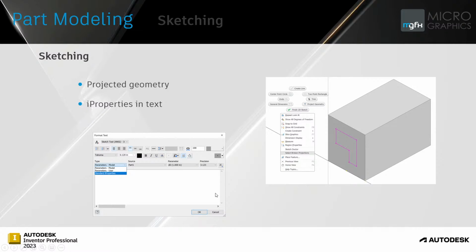The second enhancement there is you now have a way to add iProperties in a normal text entry. So when I entered that text previously for the marking, you would have seen there in the text box I have a drop down for type, and I can select standard iProperties, and I can put in things, for example, like the file name or the designer or perhaps the part or stock code number if those fields are populated.